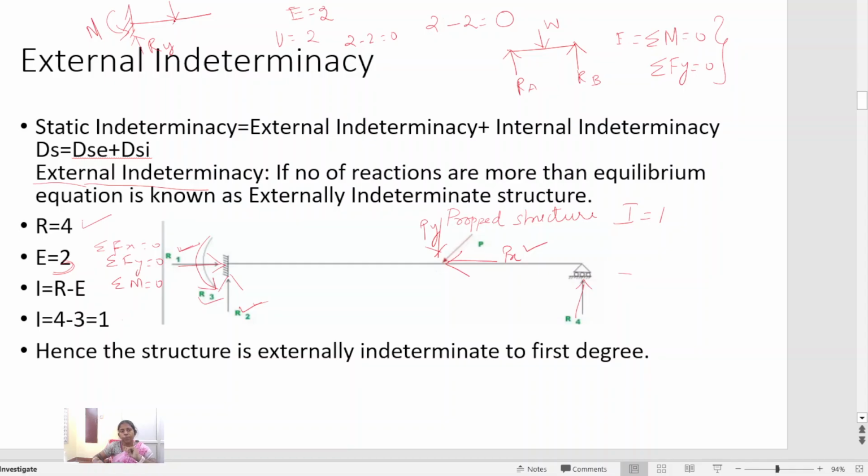Whenever the load is purely perpendicular, there is no need of considering summation of Fx. So in the general case, for a frame element or a truss element, you have to consider all three equations. In some cases of beams, we can consider two equilibrium equations. In this condition, the load is inclined, so the load is split into two components in the x direction and y direction. So there is a possibility of a horizontal force acting in the beam, so I am considering equation 3.